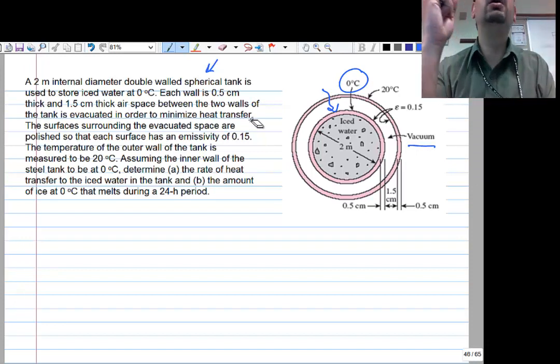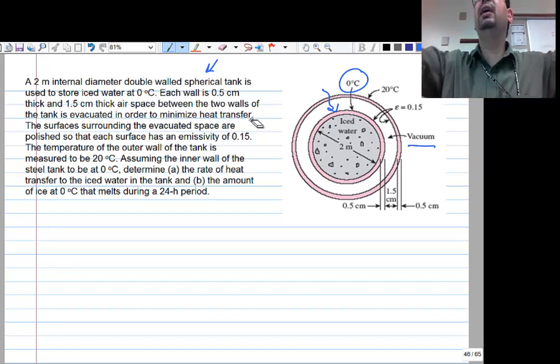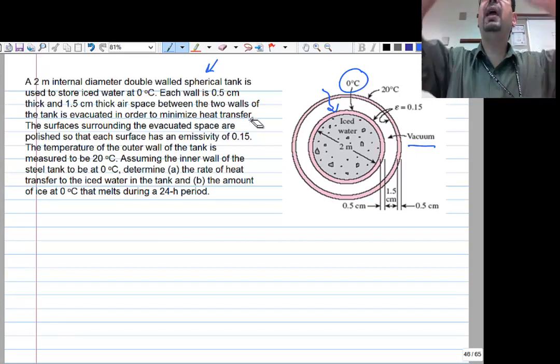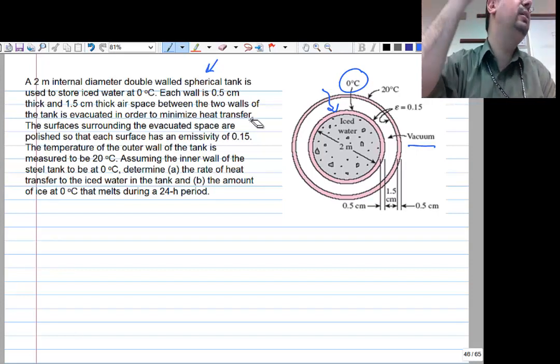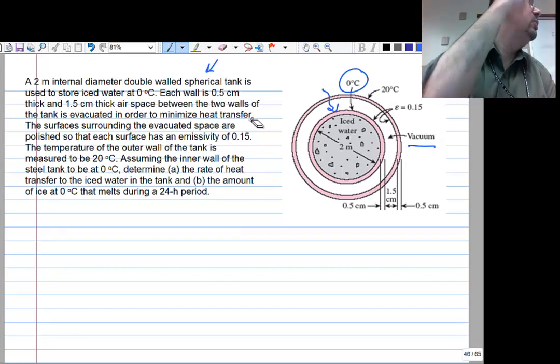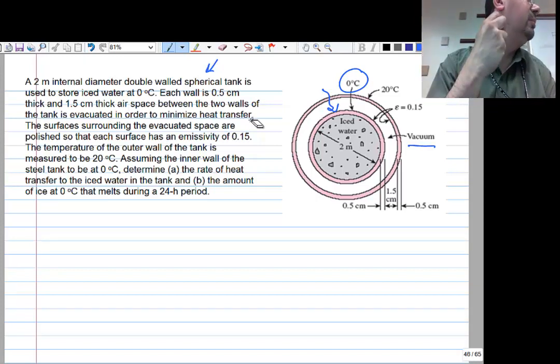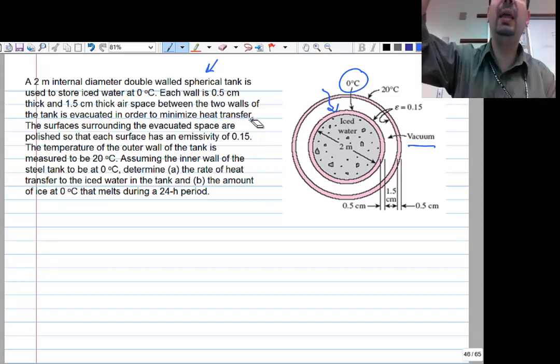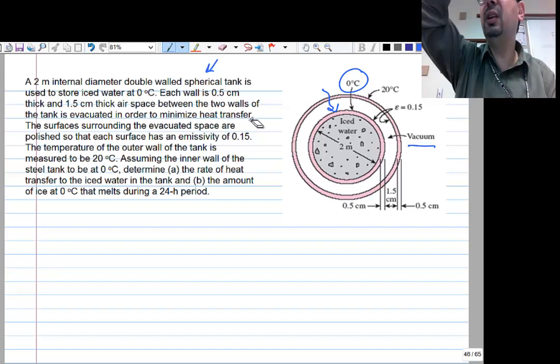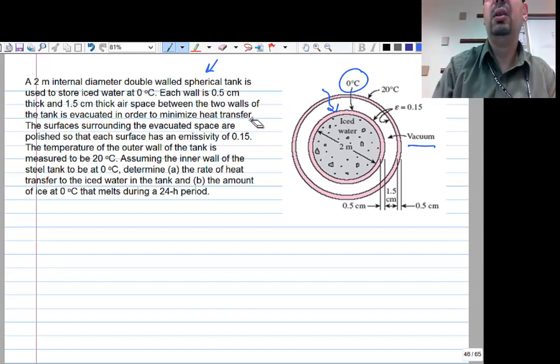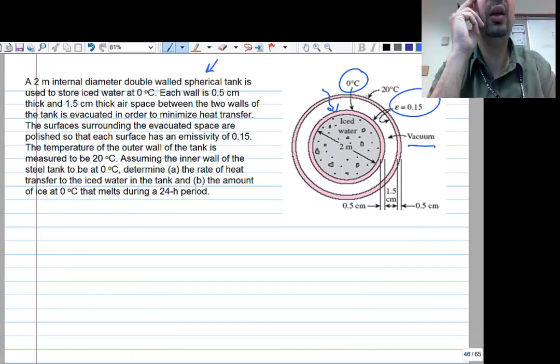So again, the soot in a fire, when you start the flame and the flame is really kind of black, those soot particles, they emit like crazy. They are the reason why the radiation is very strong in the flame. Okay, so a sooting flame basically radiates very, very strongly. Alright? So in order to minimize that radiation, they basically make epsilon 0.15.